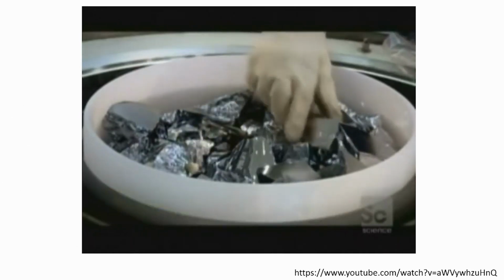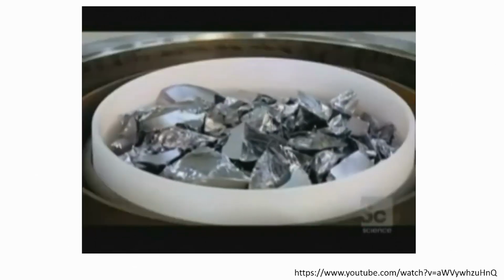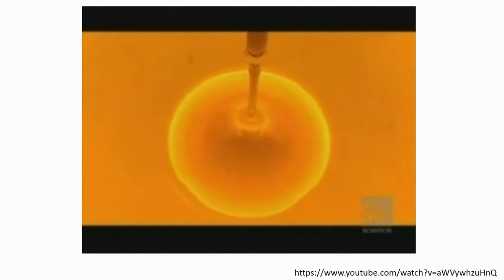They begin with raw polysilicon, or poly, heated to over 2,500 degrees Fahrenheit inside a special sealed furnace, which has been purged with argon gas to eliminate any air. The resulting lake of molten silicon is then spun in a crucible, and a silicon seed crystal, roughly the size and shape of a pencil, is lowered into it while spinning in the opposite direction. As the molten polysilicon is allowed to cool, the seed crystal is slowly withdrawn at around 1.5 millimeters a minute.